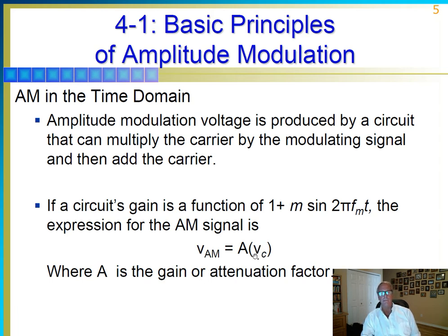The A is the gain of the carrier sine wave, basically. So basically what we're doing is amplifying the carrier sine wave using the modulation signal, modulation sine wave, if you will. Obviously, the modulation is not always a sine wave, right? If it's somebody speaking like me right now, that's hopefully not a sine wave, otherwise it'd be very boring. But for instructional purposes, we always just use a sine wave. Makes things certainly easier to write on a whiteboard, for example.